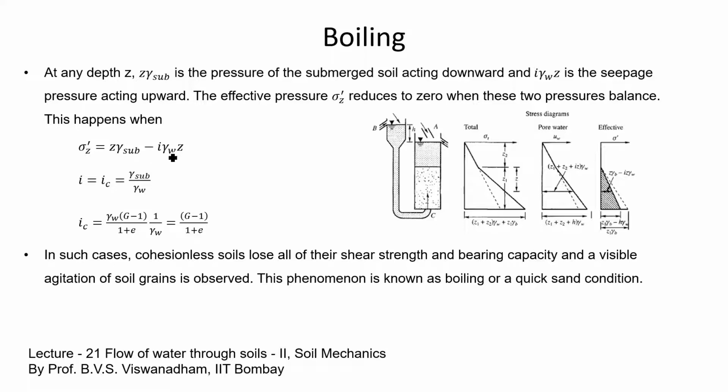When both the terms become equal, the value of effective stress becomes 0, and this condition is called boiling. When the effective stress reduces to 0, the soil loses all its shear strength and cannot sustain any extra load. That phenomenon is called boiling.